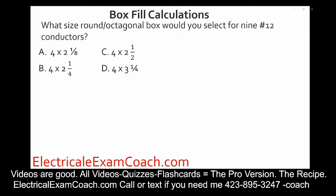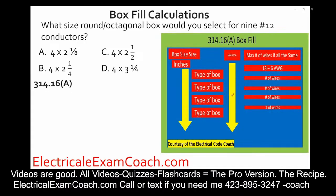What size round octagonal box would you select for 9 number 12 conductors? For this one, we're going to be using table 314.16a. We're going to start here and we're going to find our gauge of wire. Then we're going to come down and we're going to find a box, making sure to cross over and double check that we don't crest over into a different style box. We want to stay in the round octagonal. We find our conductors, we find the one that fits it, we slide over and double check ourselves, and we're going to select A. Great job.